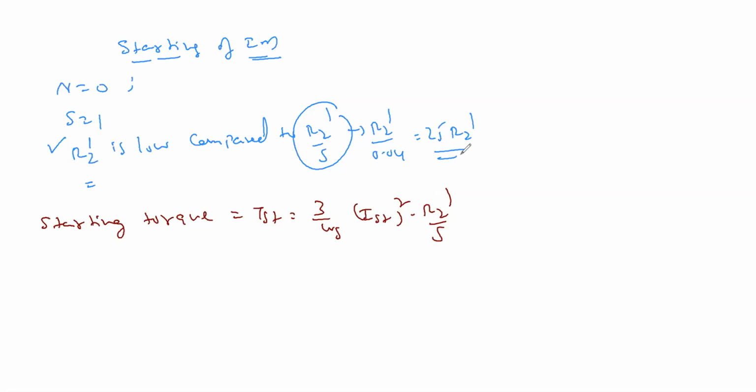So mention that point: during starting, rotor resistance is less, equivalent to a short circuit condition. And the current drawn is 5 to 6 times more than the rated current.